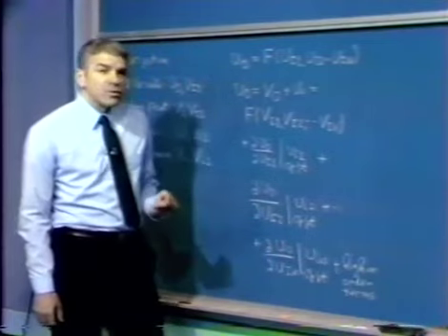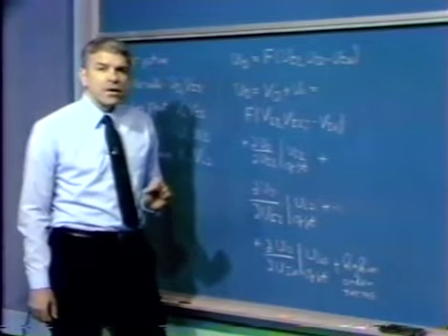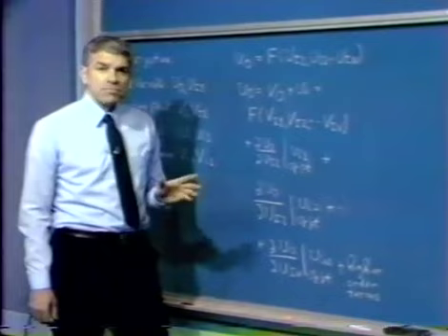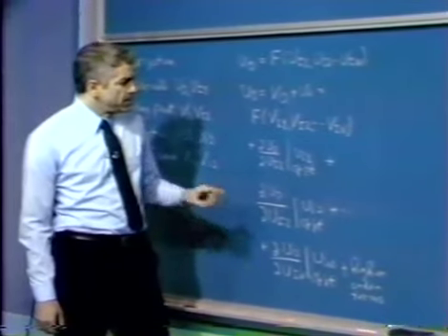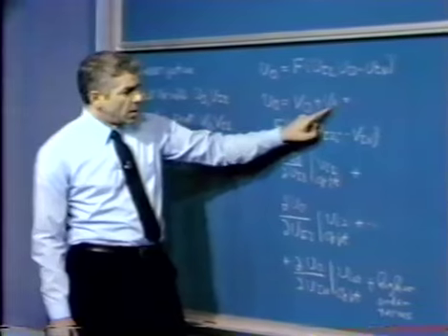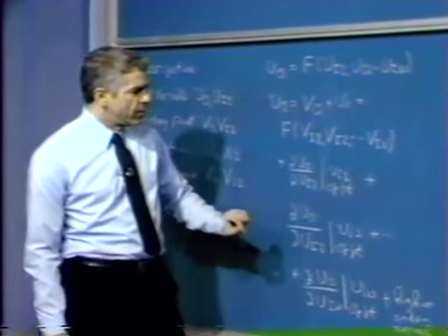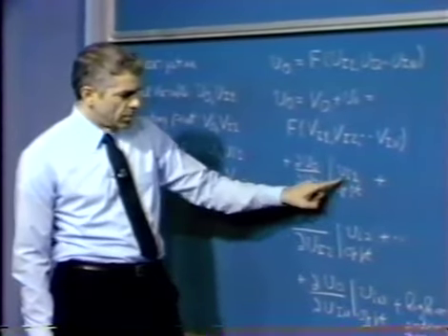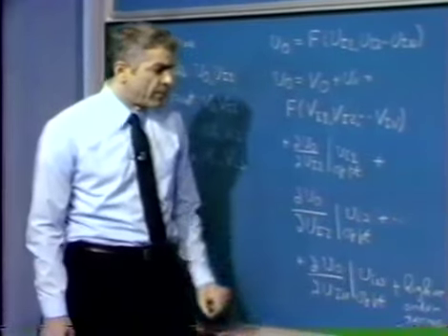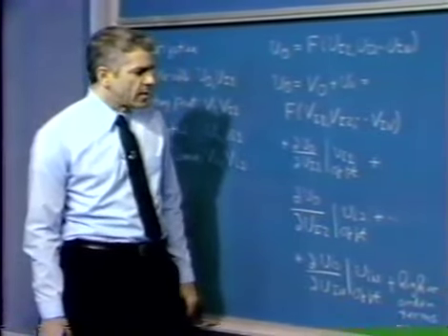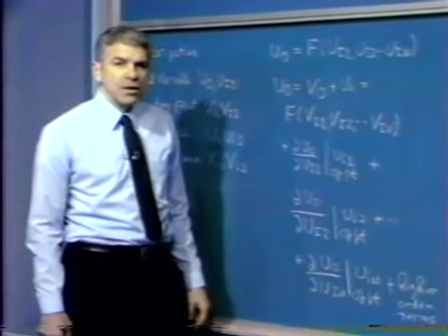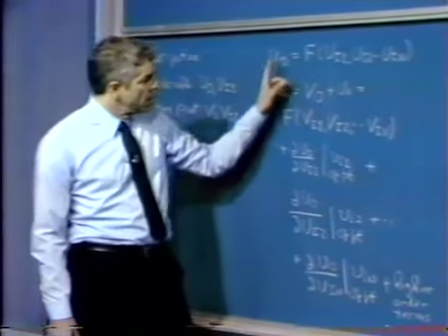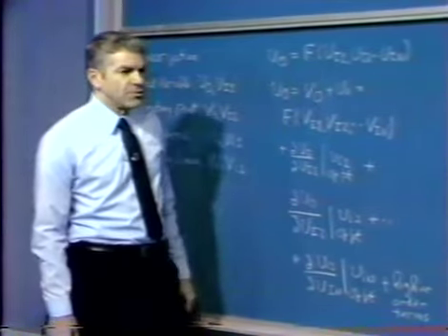And if we restrict ourselves to sufficiently small variations in the input variables, we argue that these second order and higher terms can be neglected, and we can then base our approximation on the argument that the incremental change in the output voltage is simply given by the various first order partial derivatives multiplied by incremental changes in the various inputs. And so we can use that truncated Taylor series expansion to develop a linear set of equations that describe our input to output relationship.